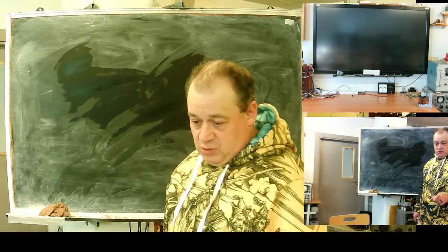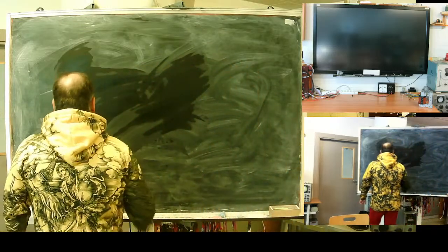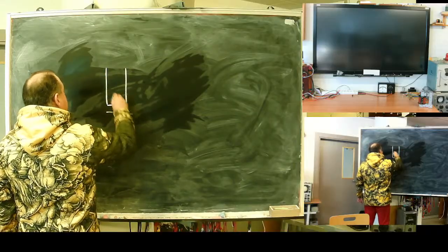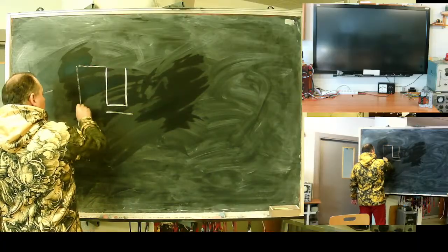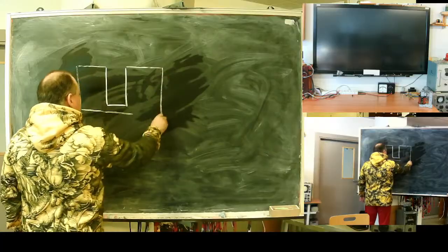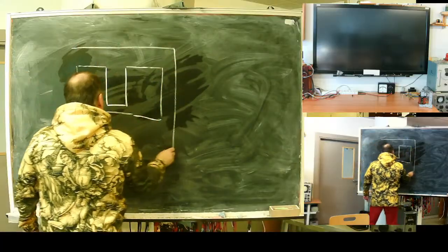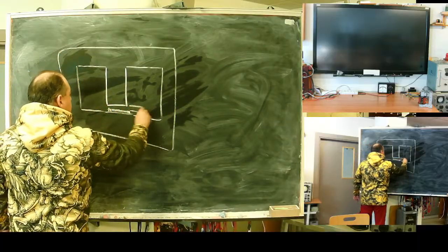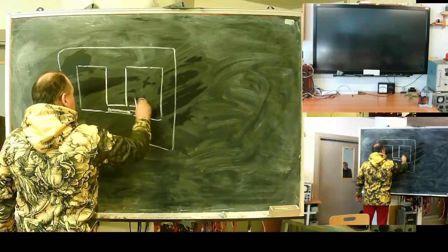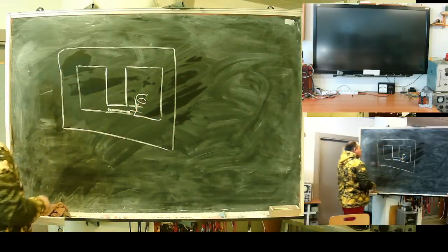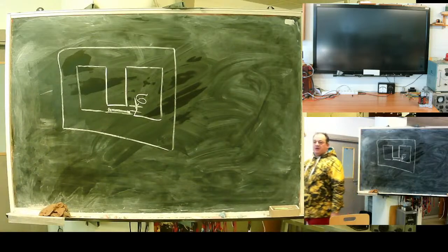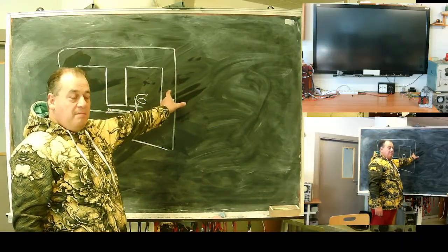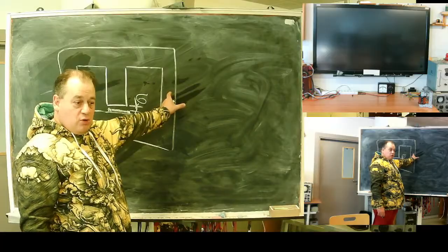Good practice for an air gap transformer is usage of a closed magnetic frame. Here, sigma is an air gap, a closed frame. The outer legs perform magnetic screening, which prevents crosstalk.